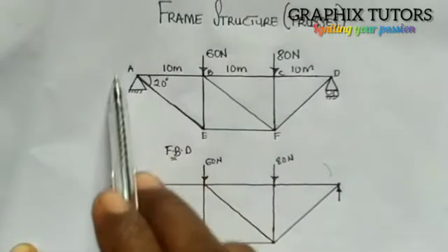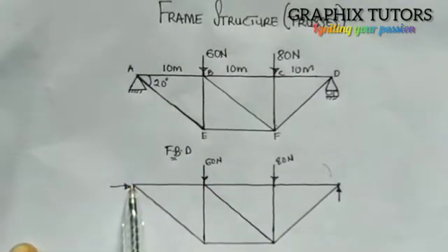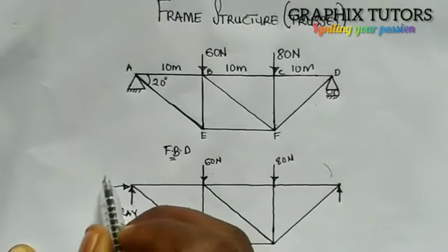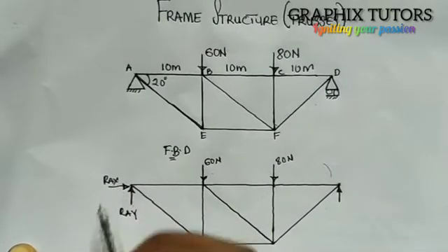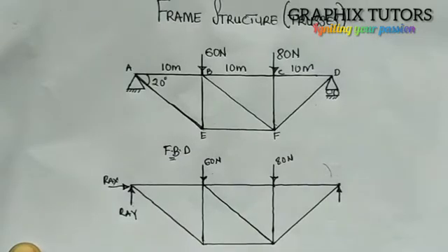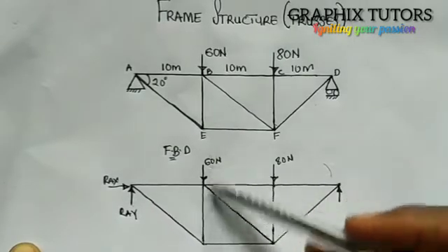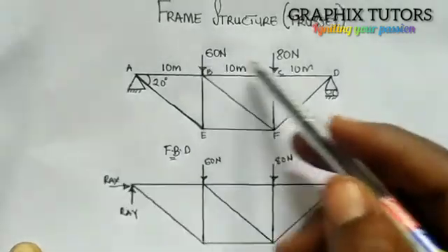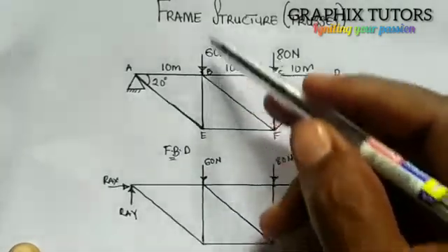Now because this is a hinge support, we're having two reactions. A hinge support at point A has two reactions. That means the reaction at point A along the y-axis is this one facing up, while this is the reaction at point A along the x-axis. Our load will always act downward. It can never act upward, right? So that's why you see all these point loads facing downward.